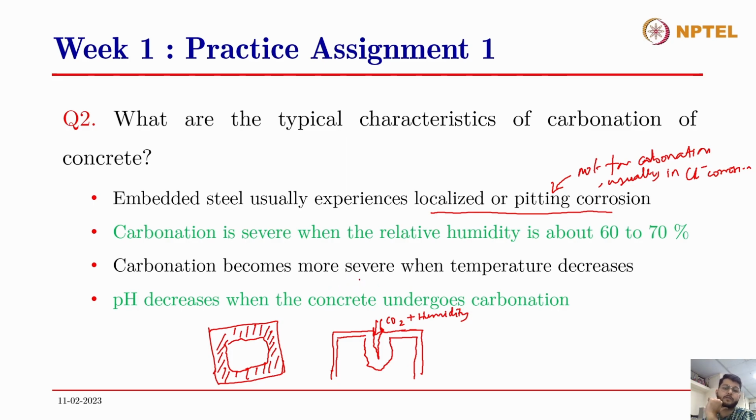The third was that carbonation becomes more severe when temperature decreases. As we know from the laws of diffusion, with an increase in temperature, the rate of diffusion also increases for gases. So this is not a right statement, because carbonation will be more severe when the temperature is increasing, provided there is sufficient relative humidity available.